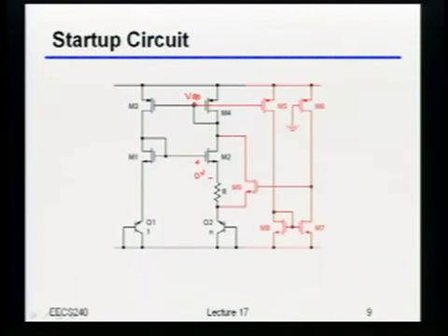Okay, well, if I have zero current flowing through here, I can detect that by just putting a PMOS transistor biased off of the same gate voltage, right? So if the main circuit has zero current, then this PMOS should also have zero current. I can mirror that over to here. And then essentially what I'm doing is just comparing how much current is flowing through this versus how much current would be flowing through this PMOS transistor where I just tied the gate to ground.